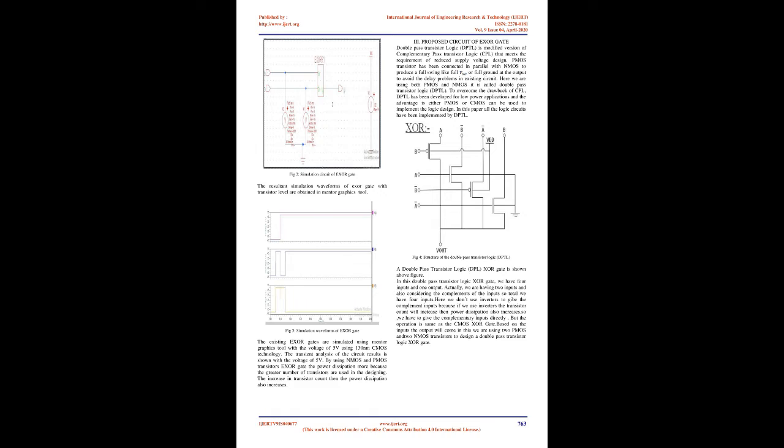To overcome the problems in complementary pass transistor logic, like noise margin and speed degradation at reduced power supply voltage, double pass transistor logic is the modified circuit of complementary pass transistor logic. Double pass transistor logic uses both PMOS and NMOS devices. The NMOS and PMOS transistors are arranged parallel to each other. Double pass transistor logic attracts much attention due to its low power dissipation.